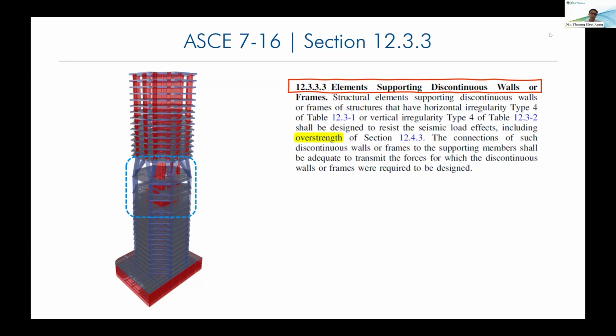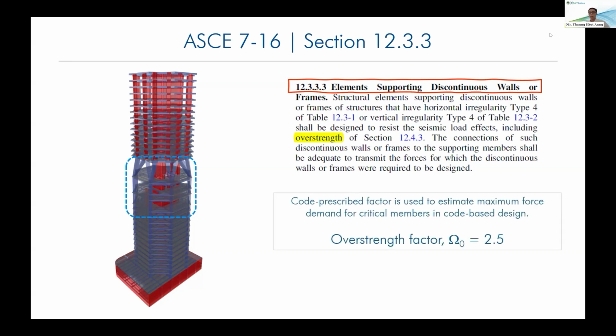materials. The material strength we use is nominal strength. When we test the actual strength in the lab, the actual yielding strength of rebar will be larger than the strength that we use in our calculation. So those overstrengths altogether will provide the additional strength in our structural members. That overstrength effect is considered with the overstrength factor omega, which is about 3.